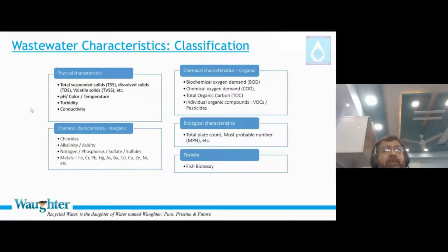But what correction do you require? If you already have M alkalinity in the water, that means bicarbonate or carbonate ions are already present. So to that extent, you do the subtraction. Suppose you get a TOC of a sample as 1000 and the alkalinity of that sample is 200, same units. Then the TOC is actually 1000 minus 200, because 200 was inorganic. CO2 was there in the carbonate ion also, and in the bicarbonate ion also. You want to measure the total organic carbon, not the inorganic carbon. So the TOC monitors need corrections with respect to the M alkalinity present in the water. I hope it was not complicated.